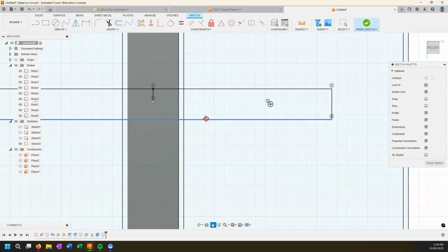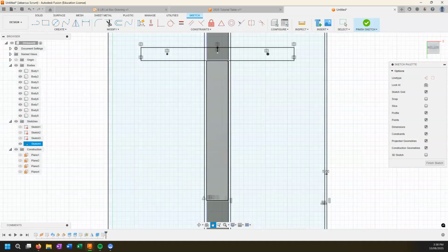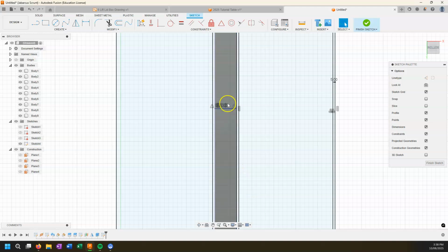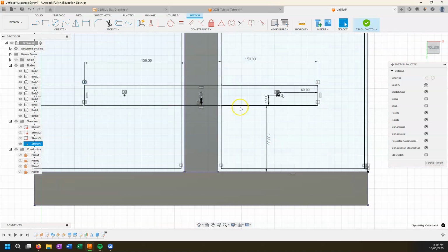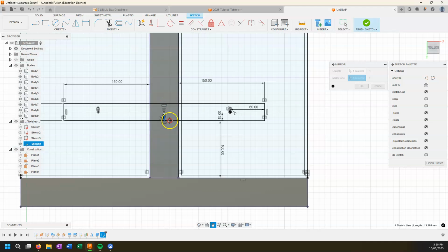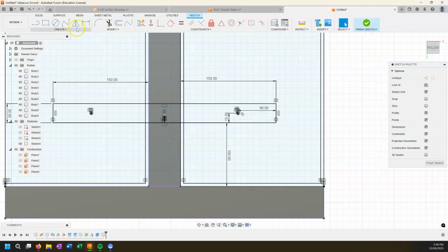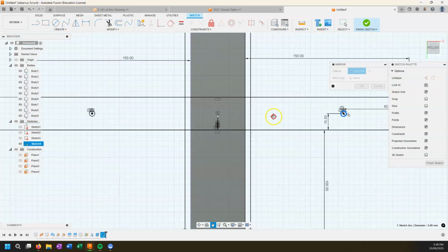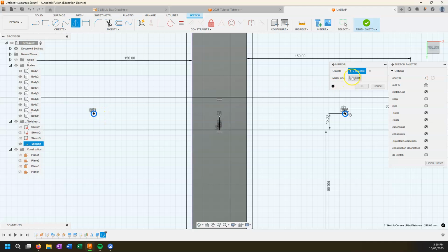Okay. Got our holes. I only got a point there, which means that first mirror didn't actually work. How do I edit mirrors? I don't even know. Anyway, now I'll have to do that one again. So when you click on the hole, make sure you click on the outside. I must have clicked on the inside before. Change the mirror selection tool there. Yep. And then we'll have to do it again. Silly, silly me. What a foolish man.